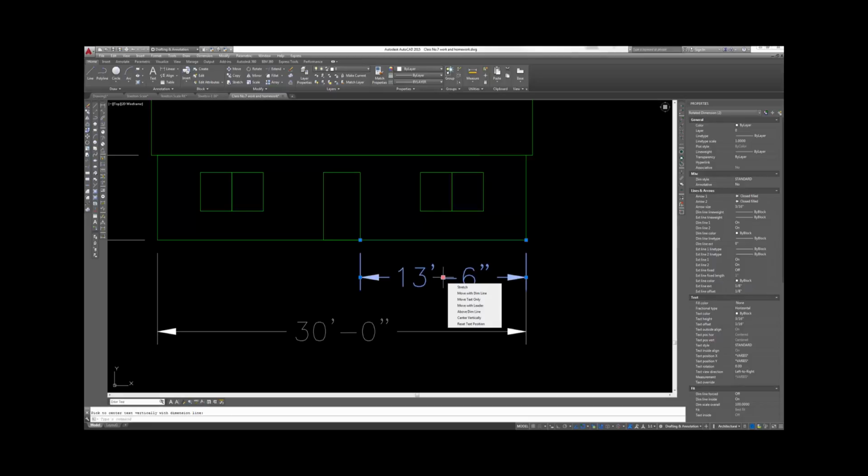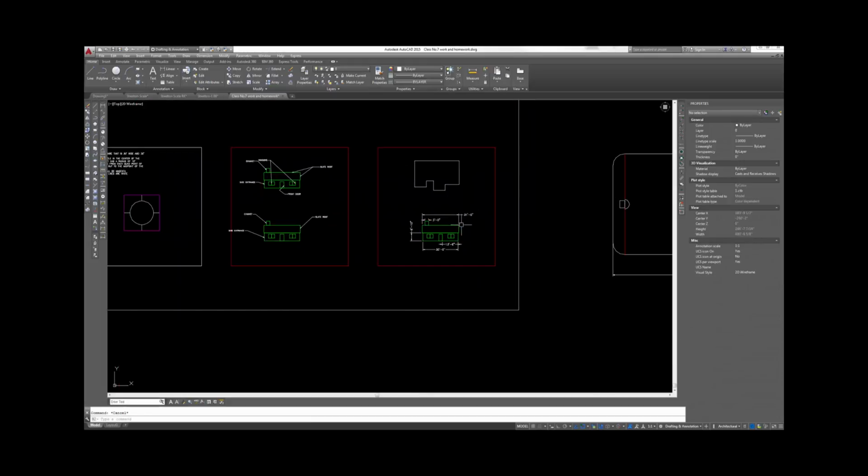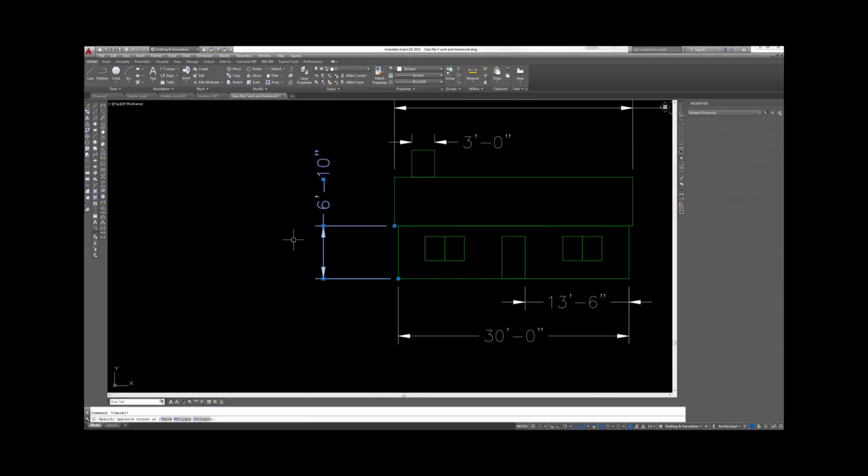That didn't do anything for this location. But over here, if you hover over the end grips at the arrows, you can flip the arrows. And since you would never just have one arrow flipped and not the other, you come over this end, hover over this square, do not select it, and then just come down, select the flip arrow. So those are some options for text.